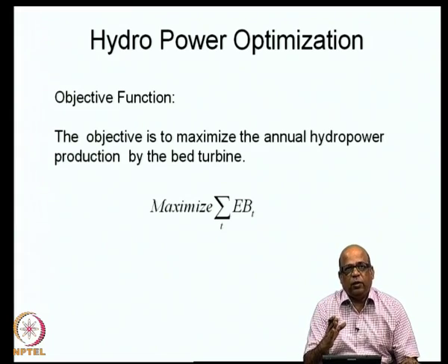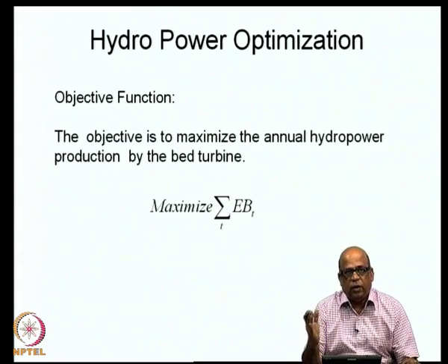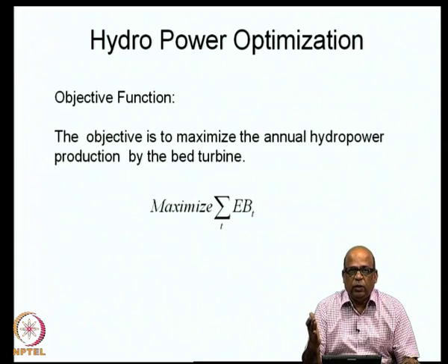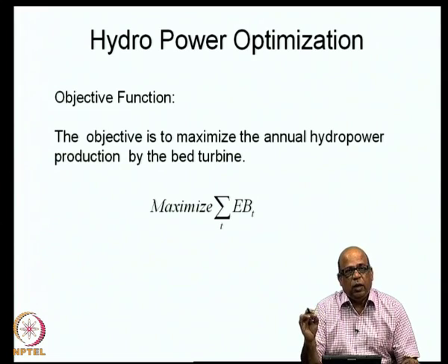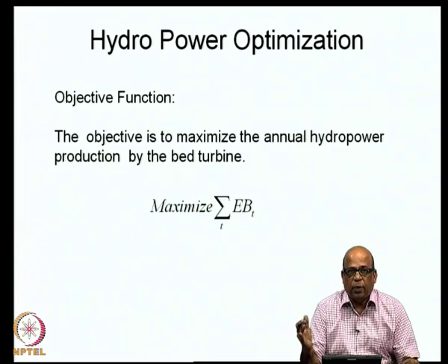We started with a chance constraint, probability of IRT being greater than or equal to DT, DT being the irrigation demands, and this probability value must be greater than or equal to P, which is a pre-specified reliability level. We want to meet the irrigation demands with a minimum reliability of P, and P may be of the order of 0.8, 0.9, etc. So, 80% of the time minimum you need to meet the demands.